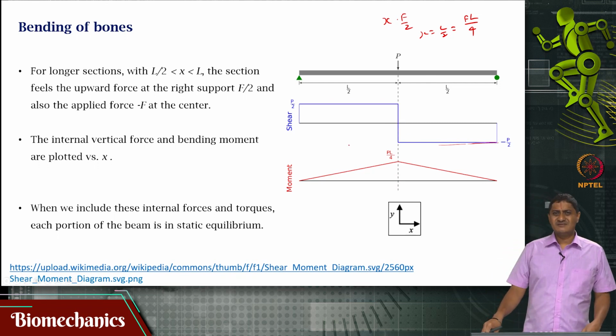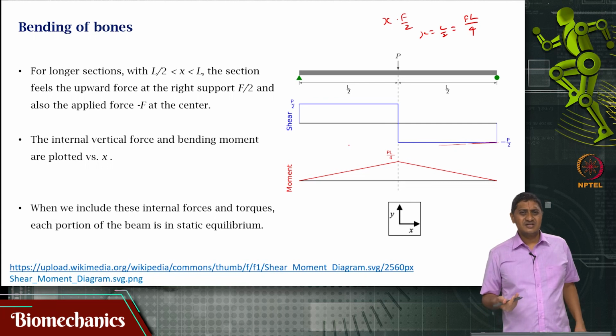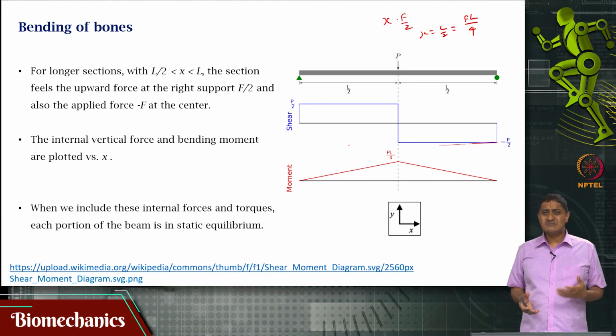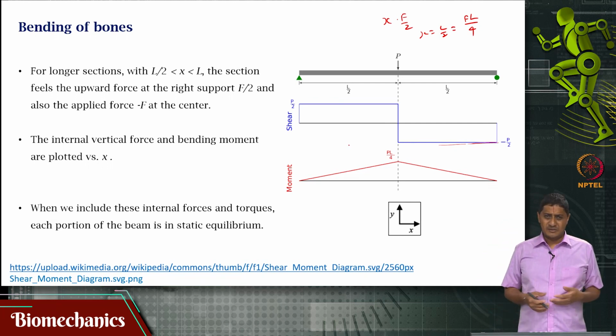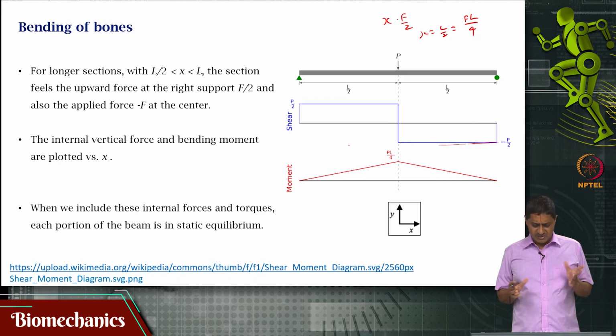These are relations that we know from statics, that also a principle is that wherever shear is changing direction is the place where you are going to have a maximum or minimum in the bending moment diagram. This is something that we know from engineering mechanics. Maybe that is a bit of a detail for you, but bear with me.